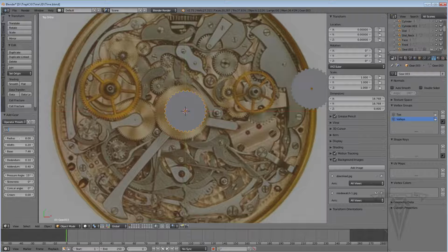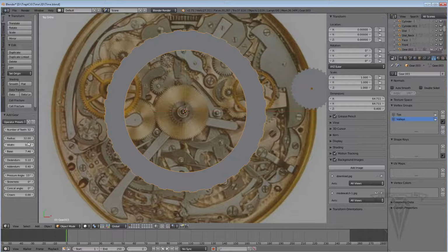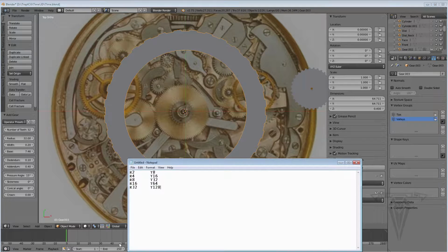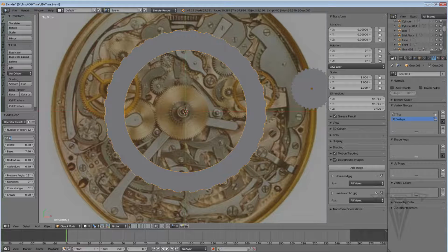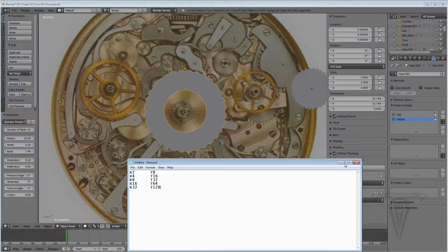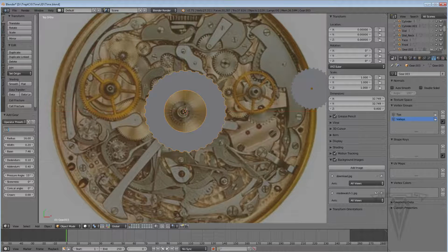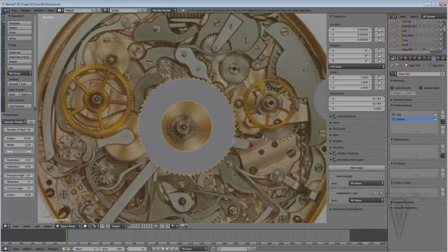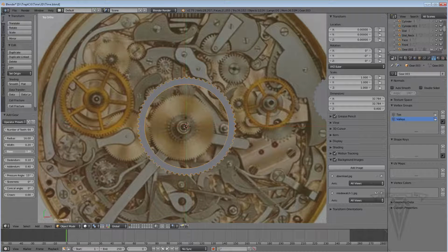And let's say a radius of 32. That's way too big. That's just going to be ridiculous. So my next radius below that is 16, and 16 comes with 64 teeth. So 64, and let's decrease the base because it's got a fairly thin structure.